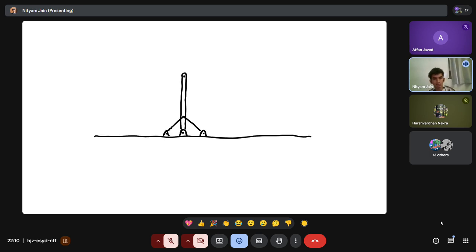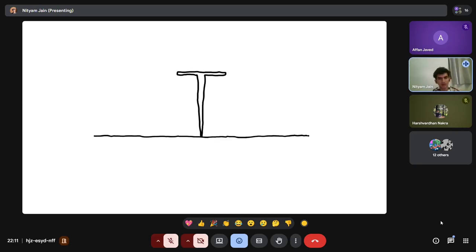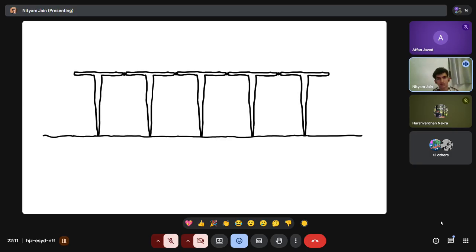Or even if it is a literal pin joint, like the detail that I showed, if it's triangulated with other members or tension cables or rods, that same thing, because of triangulation, will become a fixed joint as a whole. So even if you're seeing it's a pin joint, as a whole, it's going to act like a fixed joint. That is what people have to figure out and then see if it's a 3-pin system, a 2-pin system, or what can be the different ways it can be expressed.